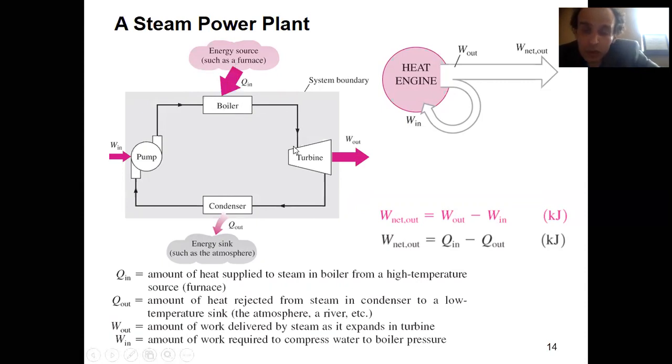And I come to a turbine. So remember how a turbine works. My turbine produces work output. That's what I need from my turbine. So I will spend enthalpy here. Enthalpy at the outlet will be less than at the inlet, and the difference will be converted into work output. Remember? Trust me, we did it last week. Okay, that's how it is.